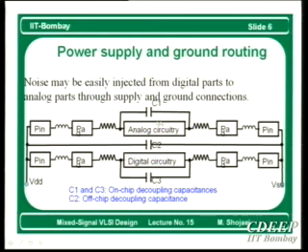This is in fact the difference between the max and min voltages I have in the circuit. So look at this capacitor as an internal battery. Then when this circuit draws a current, this capacitor simply can inject AC current. Therefore, the amount of AC current which is drawn from the inductor will reduce, and therefore we will have less bouncing on the line which is coming to the digital circuit.